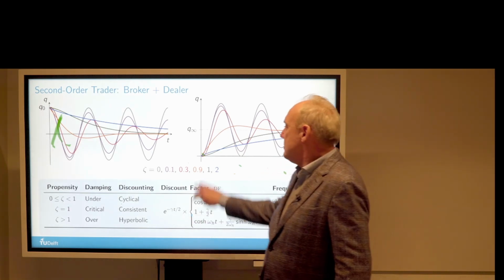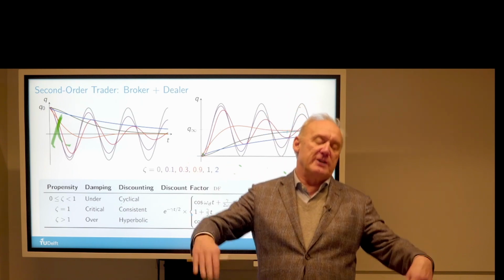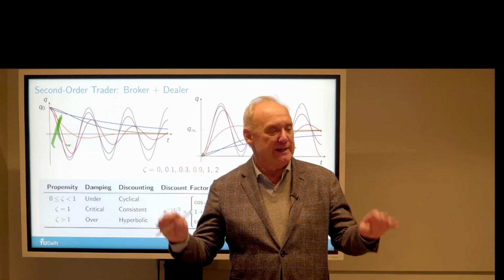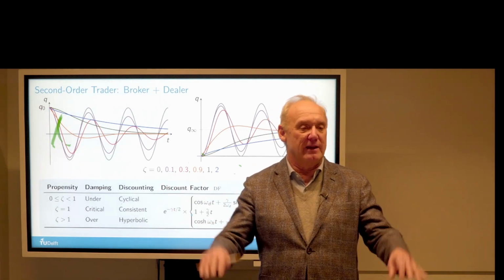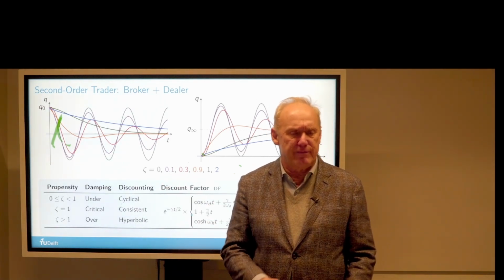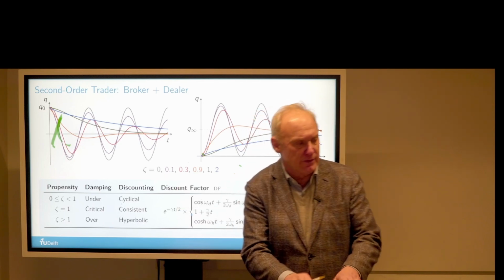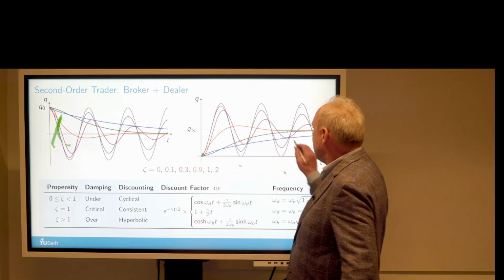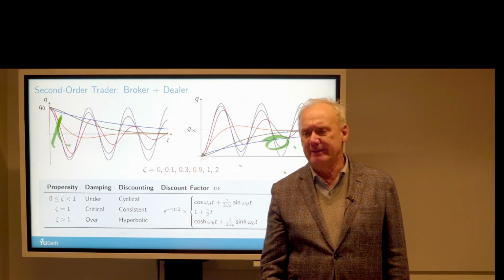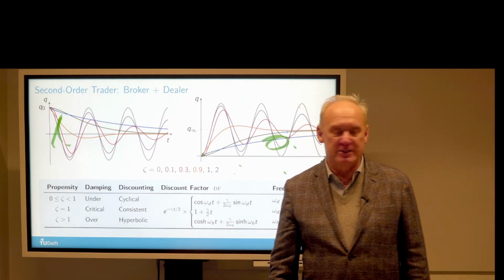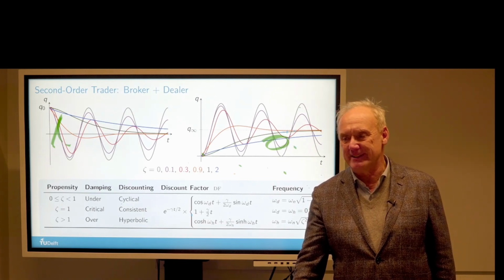If it's too underdamped, you get this feeling of swinging, like in these old American cars. You go seasick, the car going like this. So you want a little stiffer, a little more damping. You do feel the little things, but the big bumps you want to dampen out really smoothly, right? There's no point adjusting to a huge pothole, you see?